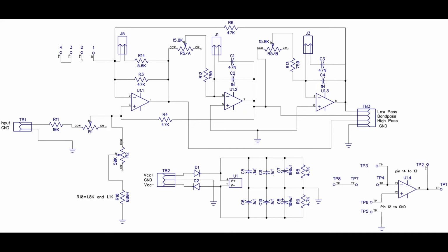Now, we have a Q pretty high. We want to reduce as much as possible any junk, any garbage on either side of the 1 kilocycle signal that we are interested in. When you have done that, you've reduced the THD of your generator to the neighborhood of 0.003 to maybe 0.005, depending on the frequency and how well you adjusted this. This can be a little finicky, but once you get the hang of it, you can run through a bunch of frequencies with no problem. It's not that difficult to use. It just takes a little bit of practice.